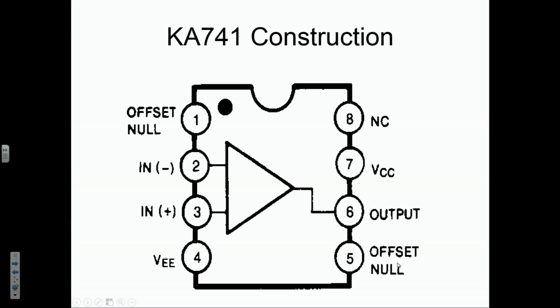8-pin chip, okay? And the pins are numbered as follows. 1 at the upper left, and you'll notice, and I'll go back and show you a picture in just a minute if I can get my cursor working here. You've got a little indentation in one corner of the op-amp, and that helps you to know which pin is which. The number 1 pin is always next to the indentation, okay? And then the numbering of the pins goes down 2, 3, 4, and then directly across to 5, and then back up 6, 7, 8.